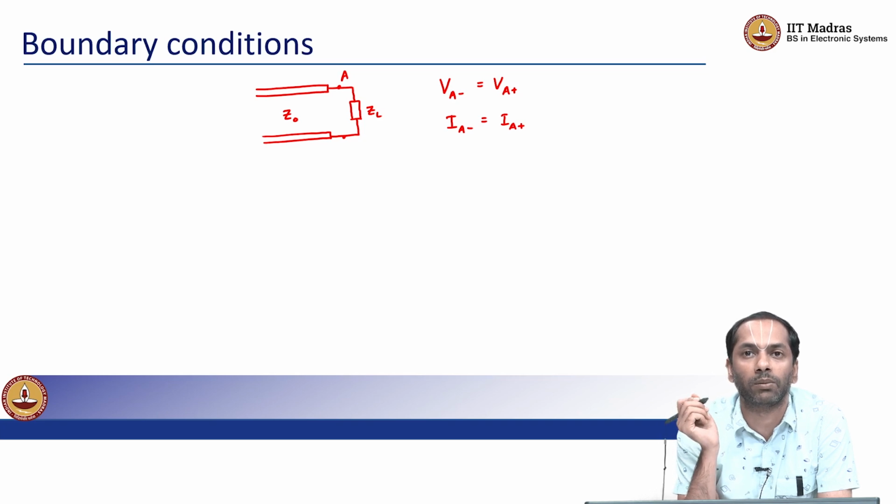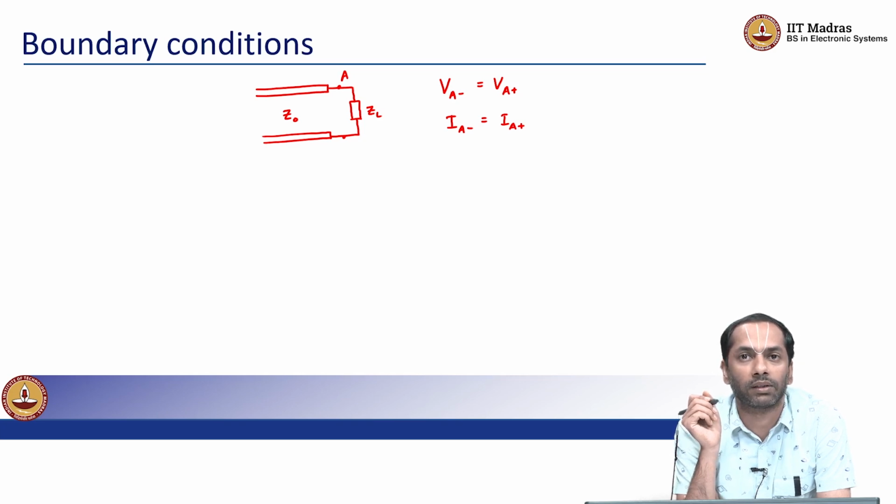The currents are equated because if they were not equal, we would expect to see buildup of charge at A, right, which would increase the voltage at A. And this, if it were to happen in a continuous fashion, would essentially lead to infinite potentials, right. So, essentially the continuity of charges, or local conservation of charges, gave us these so called current and voltage boundary conditions, right.